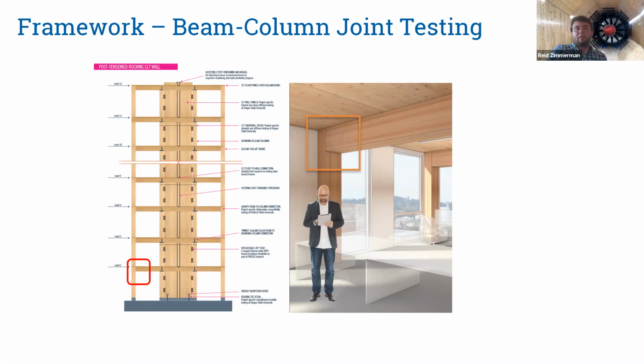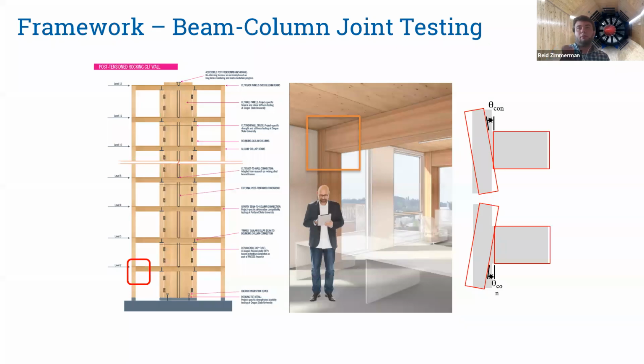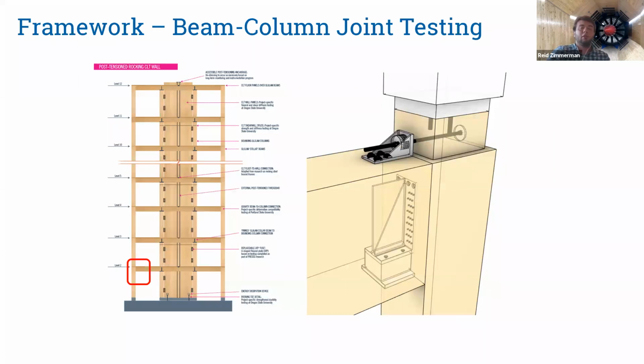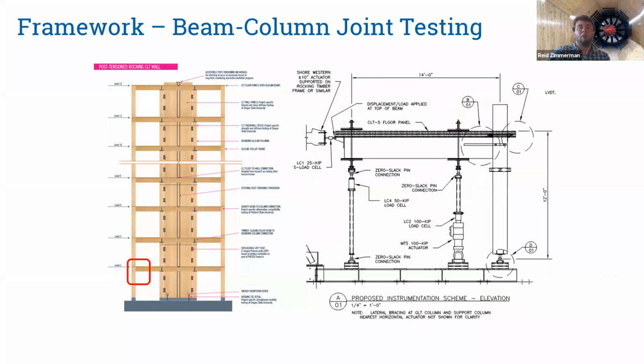So, but what happens to that very tight joint when it has to go through the deformations or the story drifts expected during the earthquake? That was a question we had and couldn't really find a good answer to in the existing research. So we developed a design of a connection that we felt could handle that imposed drift and deformation, and worked with, you almost guessed it, this time Portland State University, to test a full-scale beam column subassembly.